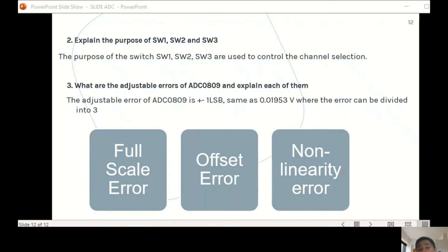Then we move to the non-linearity error. The non-linearity error is the biggest divergence between the calibration curve and a straight line linking the output signal to the applied force, known as the best fit line. This line can be established either between the zero load signal and the normal capacity signal or another more operational value.